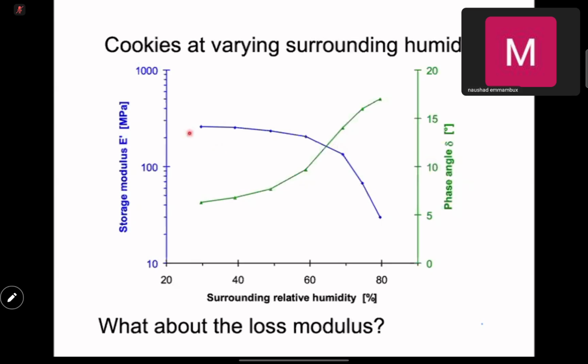You can see here from maybe about 20, 30, and it starts really looking bad at about 60. So maybe you should not store your sample higher than 60% relative humidity. That's an example. So try to keep it less than 60% relative humidity.